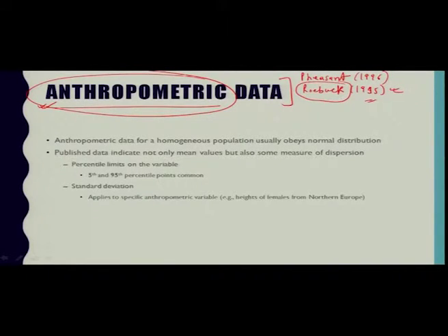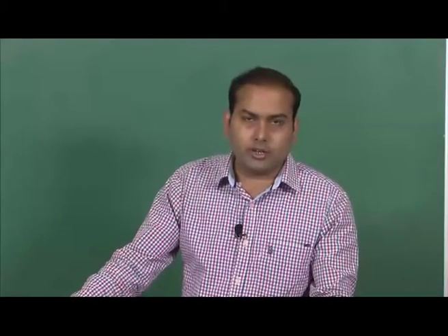Another kind of software you can think of to perform this anthropometric analysis is People Size 2000. This is a software package that allows a user to click on a relative measurement and then select age group, nationality and percentile value. In this way the software will give you the proper value of relative measurement of various parts of a body.